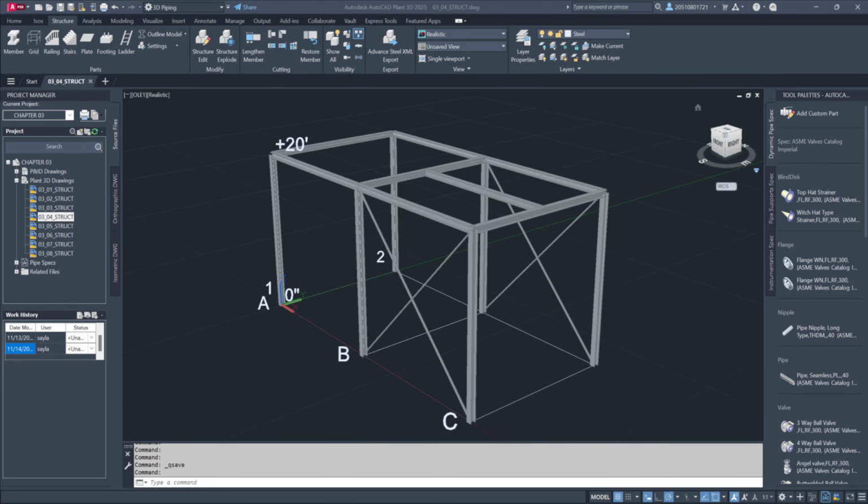Modifying structural elements once they're positioned is generally straightforward. To alter the type and shape of an existing element, you can utilize the Structure Edit button in the Modify panel on the ribbon menu, or select the beam and use the Edit Structure option in the right-click menu. You also have tools to cut, extend, and miter beams. In this session, we'll explore a few of these options.